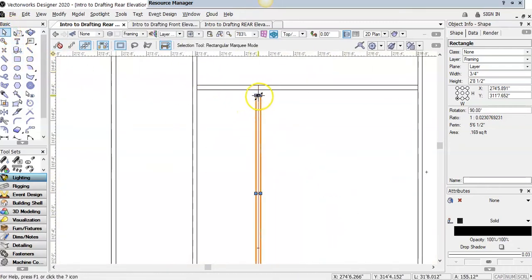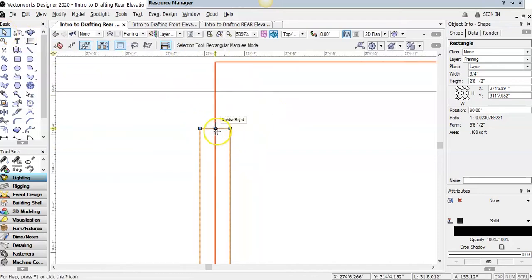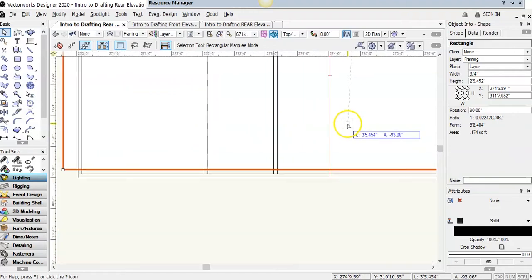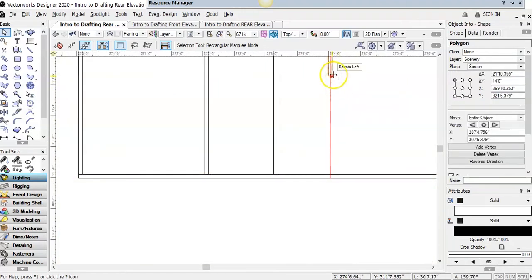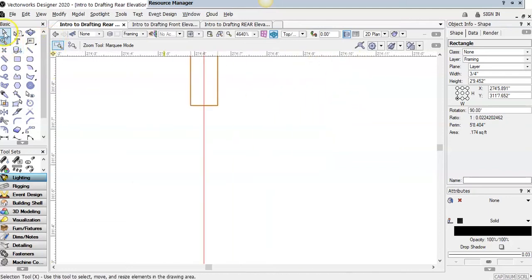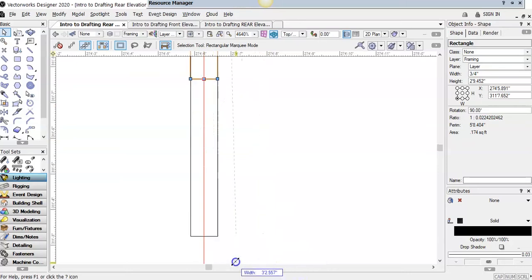One is we're just going to have this 1x4 that sort of splits the difference. But if it doesn't give you a whole lot of room to screw into, there's 3/4 of an inch, so you have 3/8 of an inch to a target to hit. So what sometimes we do is we take a 1x4 and we lay it on face. So then you have 3.5 inches to hit, but that then makes the framing a little more difficult.